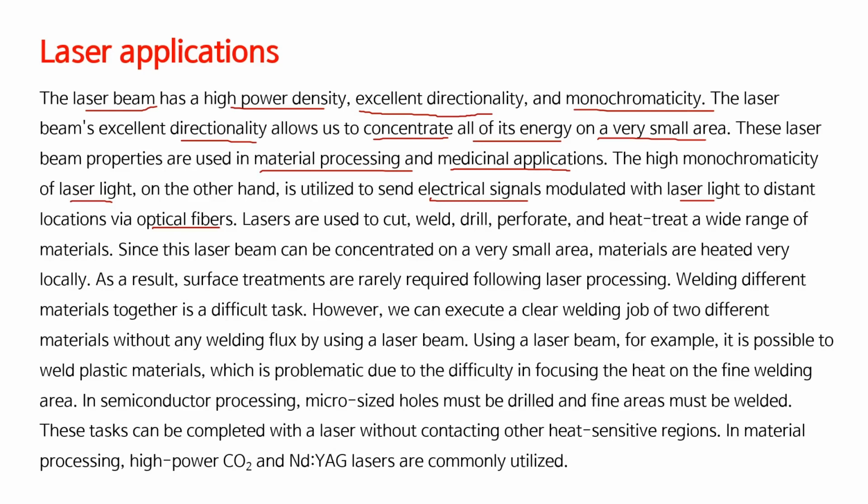Lasers are used to cut, weld, drill, perforate, and heat treat a wide range of materials. Since the laser beam can be concentrated on a very small area, materials are heated very locally. As a result, surface treatments are rarely required following laser processing.